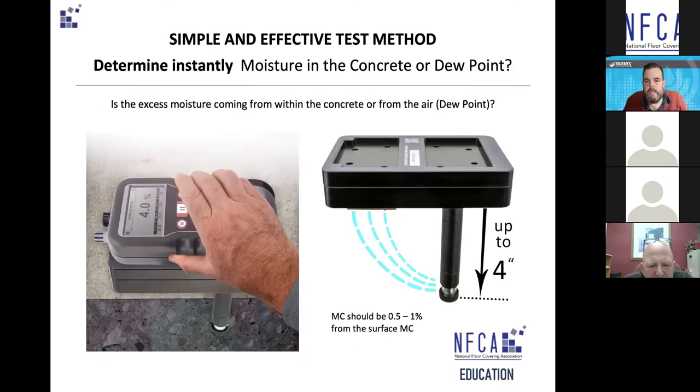So this is the impedance probe. It is designed to go into exactly the same hole that you drill for F2170. People most interested in this will be those who are doing F2170, because it gives you a piece of data without any extra endeavor to get it. It's exciting what this data is actually giving. We launched this product at a time where there was already F2170, there was already the impedance meter. So it's like adding one more piece of data.